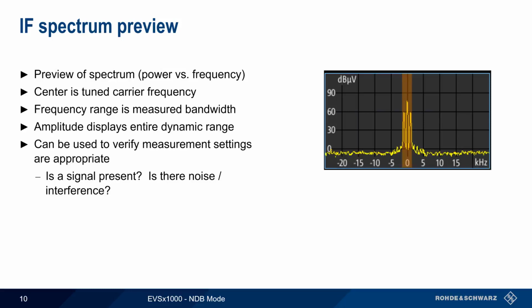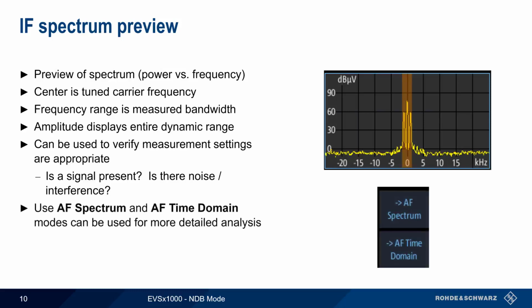Additional NDB signal analysis can be performed using AF spectrum and/or AF time domain modes. These are covered in separate presentations. Note that when switching to one of these modes, the current settings, such as the tune frequency, are transferred to that mode.